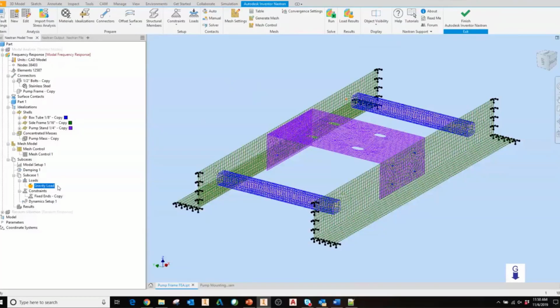So I'm going to apply gravity. I will be applying 20 modes. I'd probably need about 40 modes to really get the full modal mass participation, so I'd come back and run this with 40 as well. Damping, we're using about 5% structural, and I'm testing from basically 0 to 500 hertz with our frequencies clustered around each mode.